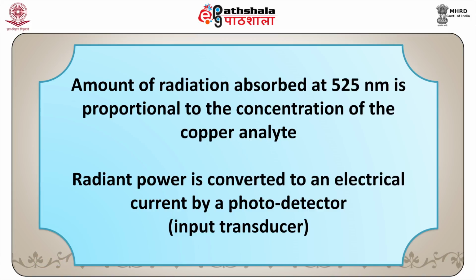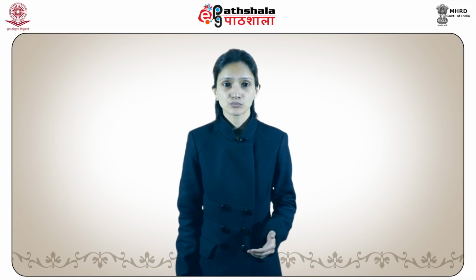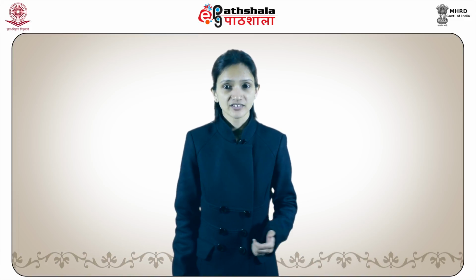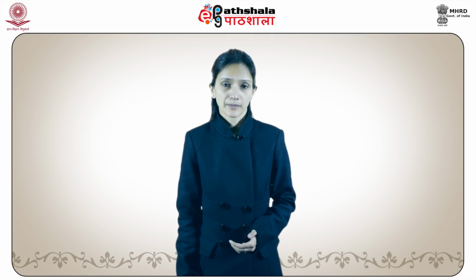The radiant power is converted to an electrical current by a photodetector, that is the input transducer. Electrical signal modifiers convert the current into a voltage and, after amplification and transformation to a logarithmic voltage, send it to the output transducer. This transducer may be a meter, a digital display or a recorder.